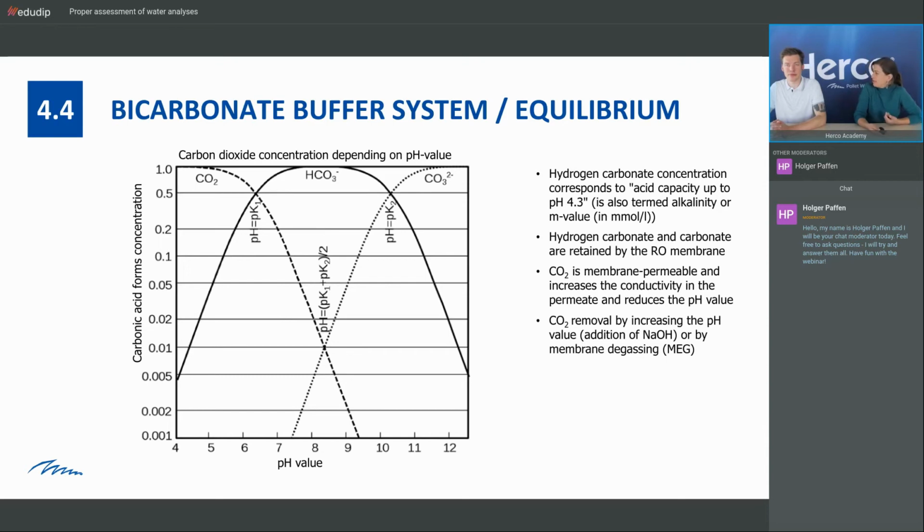That is a relatively easy option, right, with the dosing pump. Yes. Or you can use a membrane degassing stage to remove CO2, which is maybe more invest, but helpful if there's a higher concentration of CO2. Yes, and you don't have the handling with the chemicals, of course. That's also true. I think most of the EDI systems we have usually have a membrane degassing stage if it's a problem at all. Yes, absolutely.